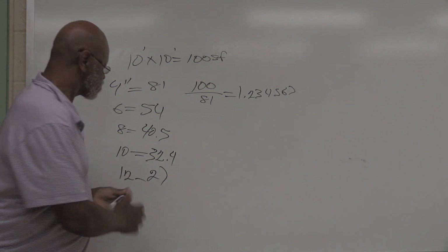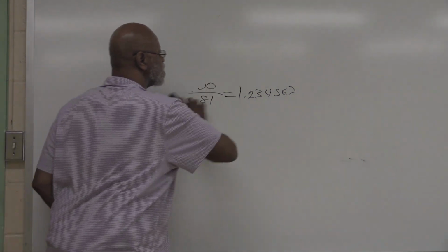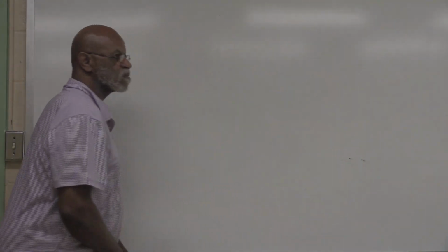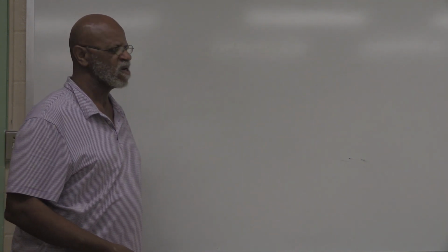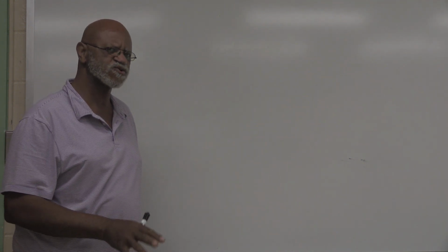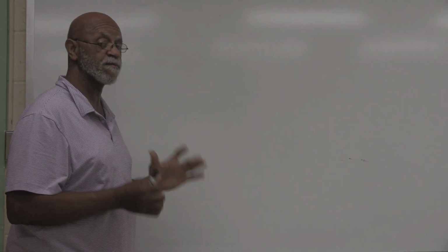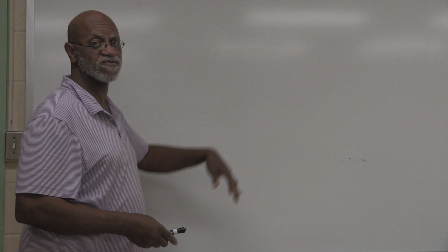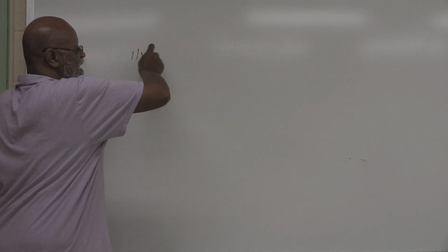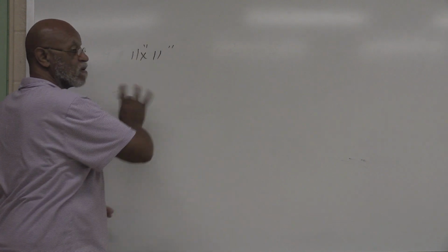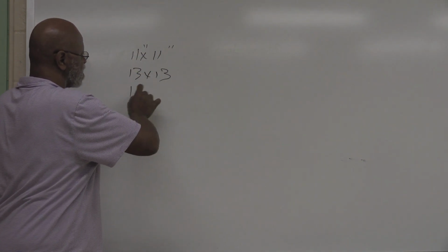Okay. I want to give you also tile. So rather than taking the traditional methods to calculate for tile, which is kind of painstaking, I'm going to give you a direct number of tiles based on 100 square feet, that 10 by 10 room. Let's say we're going with 11 by 11 inch tile. And let's say we're doing 13 and 15.